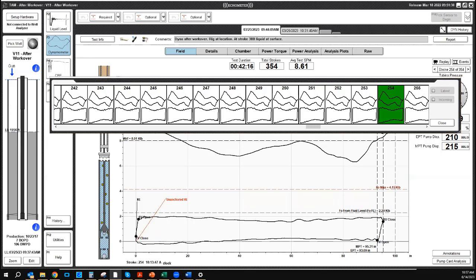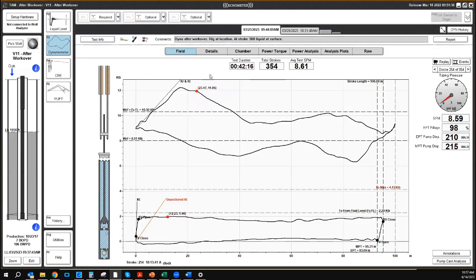Another question, Justin. Can I use the PRT to conduct a valve test if it doesn't measure real loads? Yes, and I can show multiple examples of that. The PRT will be able to calculate the pump cards and will be able to calculate the load difference. And you can see how the load changes when you stop the unit, when you stop upstroke to test the traveling valve, or stop during the downstroke.